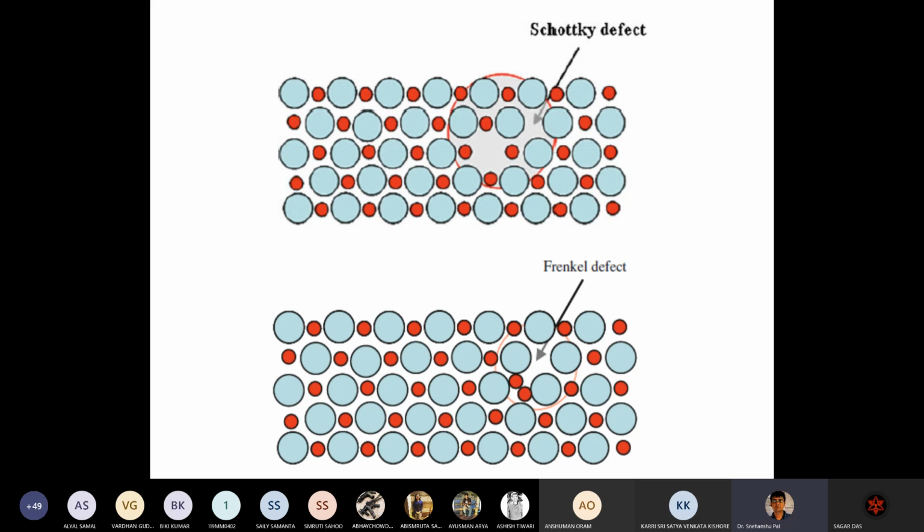Depending upon the source, in case of semiconductor or such kind of electronic materials, point defects are classified into two categories: intrinsic as well as extrinsic. When defects are created by displacement of own atoms in an impurity free crystal, they are named intrinsic defects. Therefore, vacancies and self-interstitials are considered as intrinsic defects.